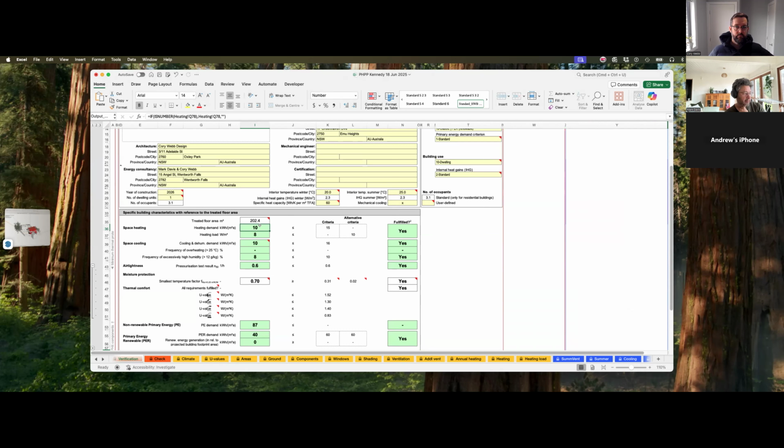A range hood impacts it that much, does it? Yeah. We've got to account for the range hood sucking out warmth and coolth. The only time it doesn't affect it is if we have a recirculating range hood, and I wouldn't recommend that because they're not as effective. Fair enough. The building code doesn't allow recirculating range hoods anymore. You can use them with the performance solution.